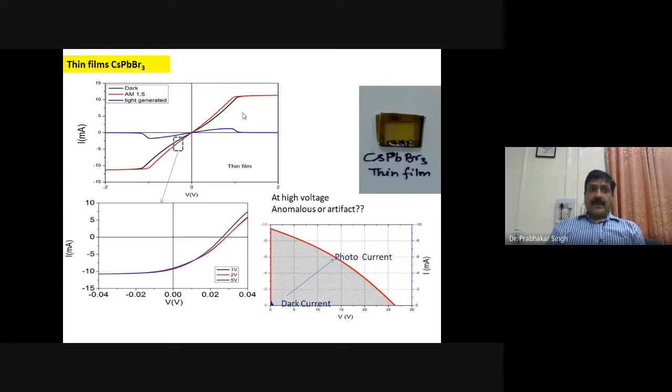Yeah. And when we measured the IV curve, we found that, of course, because this is not a cell, we only took CsPbI3 and did not put any electron trapping or hole trapping material on either side. Then we tried to measure the IV curve of the bare material of CsPbI3, and we found a small current, which you can see in this fourth quadrant.